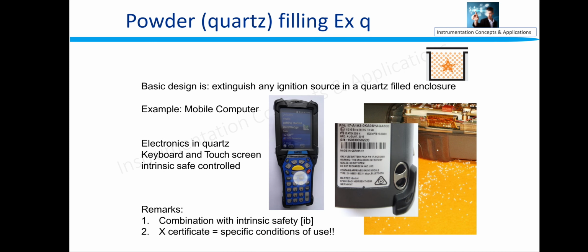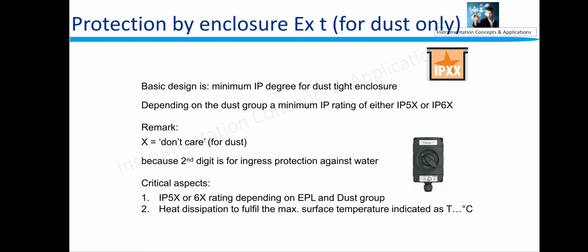Powder quartz filling: the basic design is to extinguish any ignition source in a quartz-filled enclosure. So in this equipment, if the quartz is filled, any spark that is generated is consumed by the quartz. Examples are mobile computers and electronics in quartz, with keyboard or touch screen intrinsically safe controlled. Combination with intrinsic safety, X certificate and specific conditions of use.